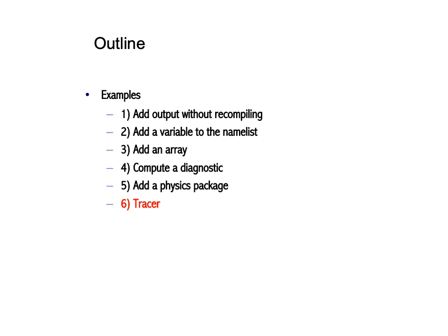This last example for this presentation shows us how we can take advantage of some of the 4D arrays that are inside of the WRF model. The WRF model has a 4D array for all of the moist species, vapor, cloud, rain, and that's called moist. The WRF model has a 4D array for the scalars, number concentration for a number of fields.